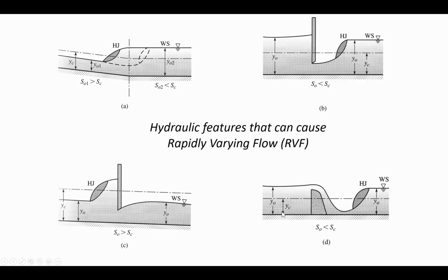Rivers are just made out of rock and gravel and soil, and if you have water that's moving very fast, it can sweep away sediment, and it can dig through the channel and move things downstream that you'd rather have stay in place. It could erode the footing of the dam if we're not careful about that. So dissipating energy after a spillway is an important part of managing hydraulic jumps.